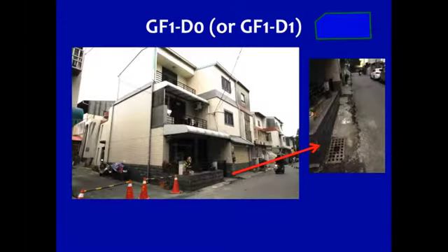This pair of photos is one of those vantage points, articulating the nominal ground failure graded as GF1, where settlement of the structure is observed. You can see the manifestation of perimeter settlement in ground feature, which we categorized as GF1 here. The damage to the structure, however, was only cosmetic in nature, graded as a D1 in this case, despite the manifestation of the settlement. There is certainly a lack of significant structural damage, likely due to the well-connected and continuous foundations of this building.